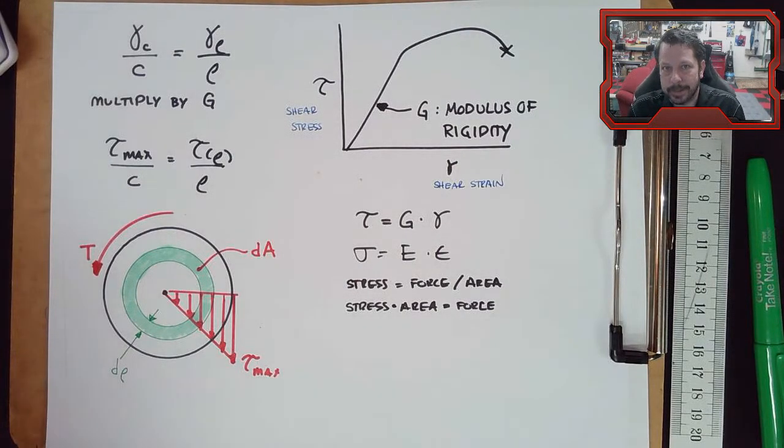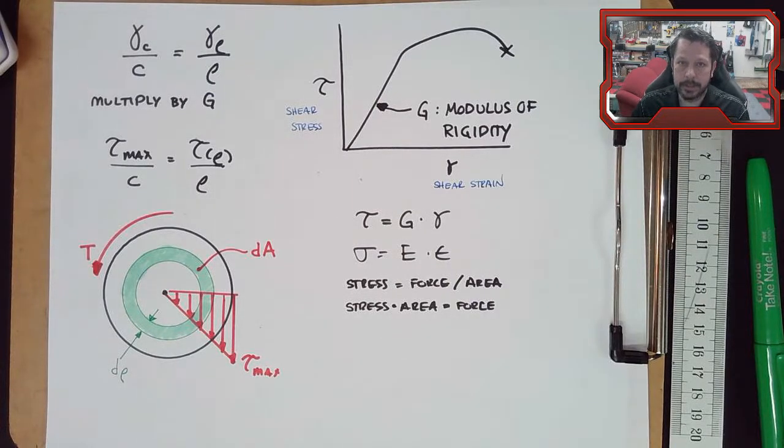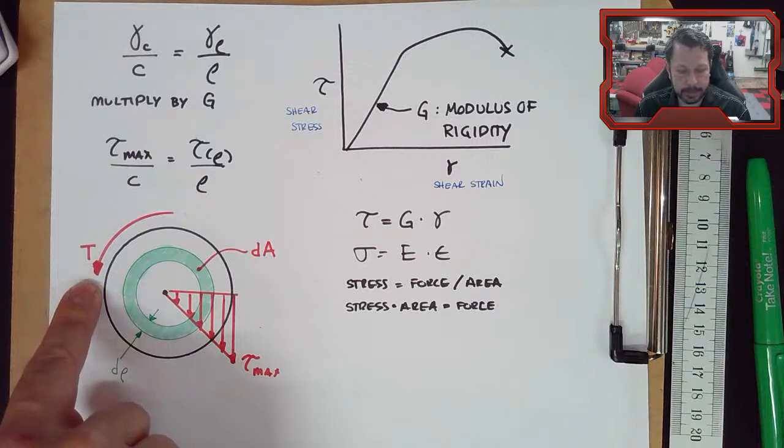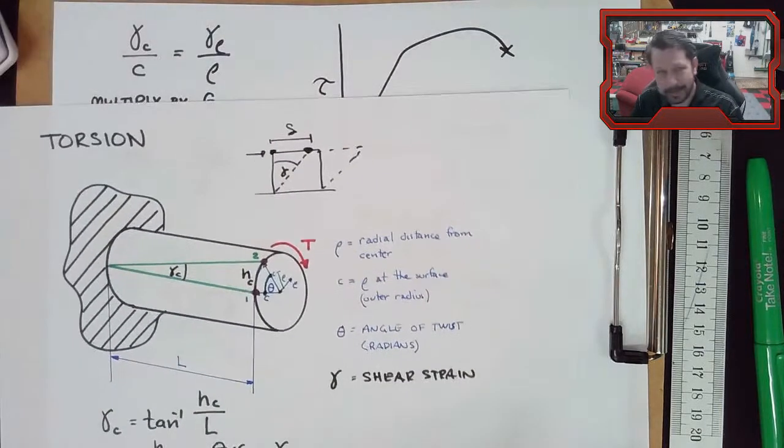Now in engineering, we use torque and moment. They're really the same thing as far as the way you would calculate them, but we use a specific word in a specific scenario. So when we were doing beams and trusses and frames and all that, we were using the word moment to talk about how a force was applied at some distance and it created some kind of bending or flexing or even a rotation. Torque, we're going to specify that a torque is the same idea.